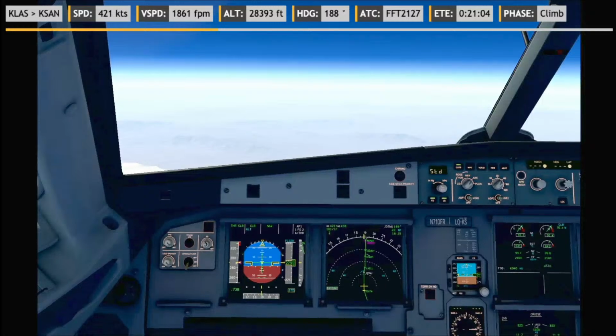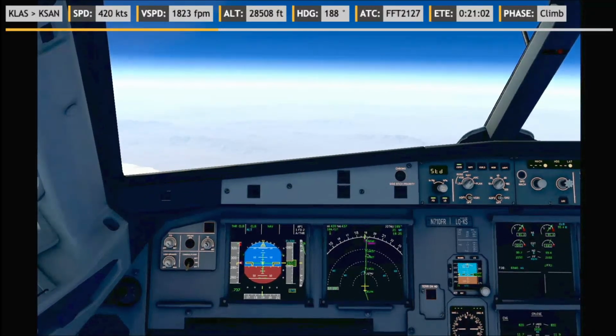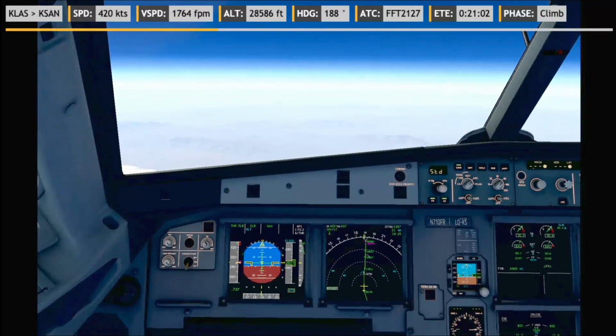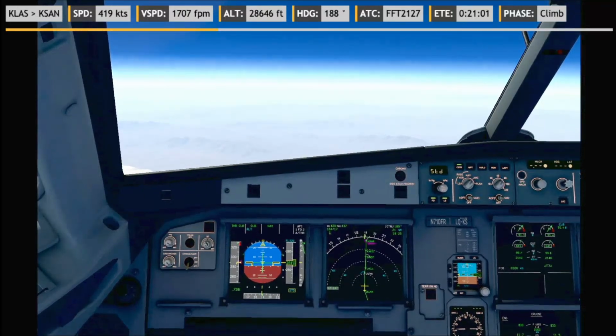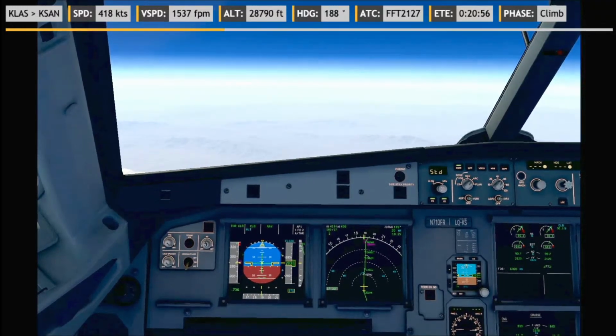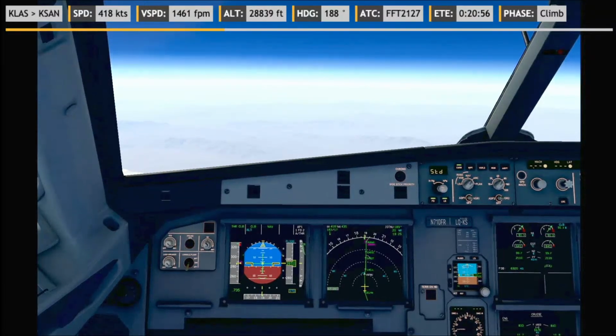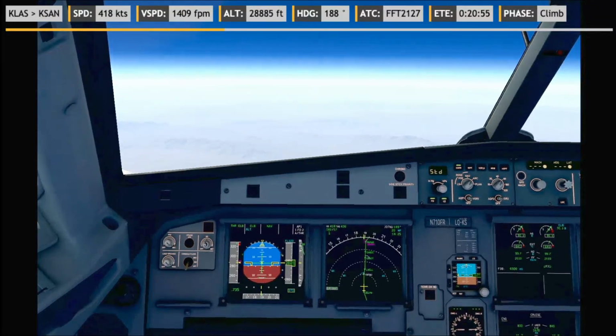And then it's only altitudes at or above. Except Lucky is at 6,000. Lucky 6,000 and then Lindy at 210 knots, 5,000 feet or above. So we want to be at 5,000 feet at Lindy so that we can start our approach at the perfect altitude. That is our goal. Then our approach briefing.